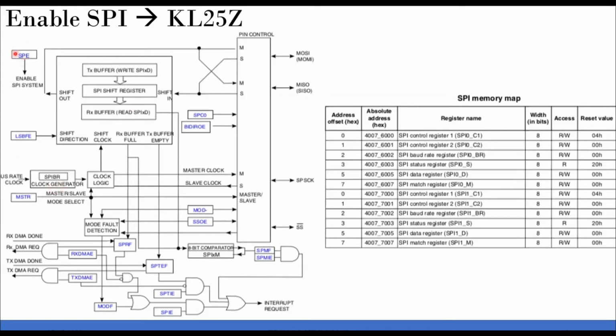This is to enable the SPI. Please go ahead and do that. All these commands are there inside these registers. All these values we can set using these registers. And if you see here, the clock control is here. So there is a baud rate control as well. You can control it similar to that in UART. So this is a clock rate. The rate at which you want to enable the transmission is configurable, and it's in full control for you. You can do it using software. You don't have to change anything. And this part, the bottom part, is to enable the interrupt and also to enable direct memory access transfer.